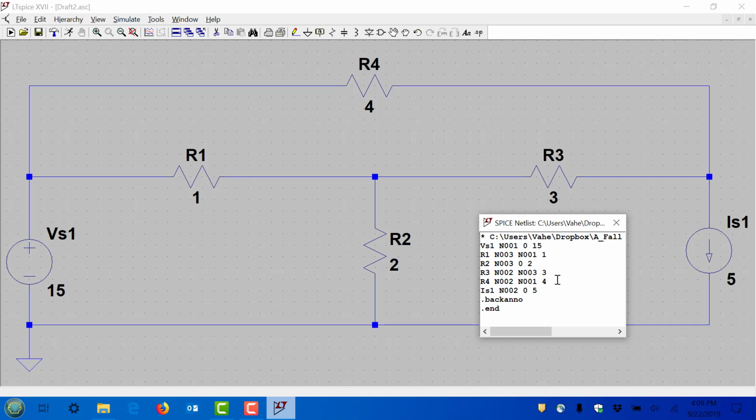Now for resistors, it doesn't matter which way you connect them, because we don't know if the current is going to flow left to right or right to left. For the voltage sources, it's important to know if the current is flowing from top to bottom or bottom to top, because that sets the current. But for resistors, the currents and voltages are calculated. So where we say VR1, IR1, that's what we choose based on Ohm's law and our arbitrary direction initially. I mean, they have to line up with passive sign convention. But if VR1 is from left to right or right to left, we don't know if our number is going to be positive. If you go back to some of the homework you did, you will see this.